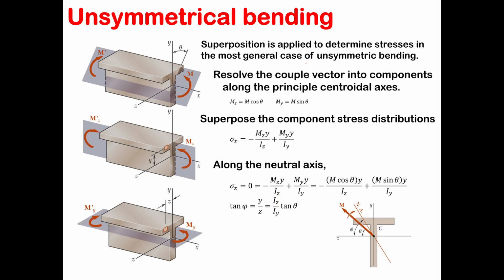So essentially, if you have an irregular bending moment, which is not applied to the plane of symmetry of your beam, and you are interested in finding the neutral axis or neutral surface, you can always find the moment of inertia in the two different directions and find the angle your moment makes with your plane of symmetry, and you should be good to go.